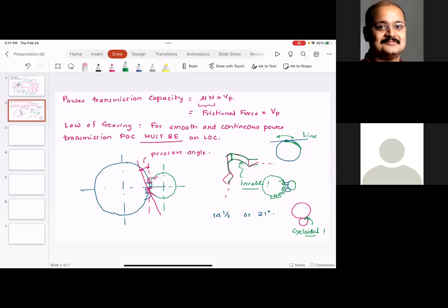Okay. Now there is something called a full gear and something called a stub gear. So what is a full gear? Full gear means you have a gear something like this. You design the gear and purchase the gear, and this is the gear. Stub gear means usually the top part is shaved, so the top part is removed, like a stub. There are certain applications for stub gears.